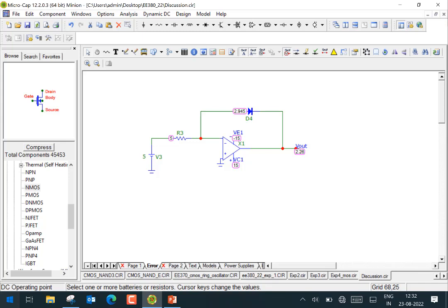No, power supply is also fine. You go and check. There is indeed plus 12. There is indeed minus 12. Power supply is also fine. So op-amp is fine. Power supplies are fine. Diode is connected in the right manner. We took out the diode and put a resistor there. If you put a resistor here, you would expect some kind of a negative voltage here, right? Still positive voltage. Still positive voltage, no virtual ground, right? So what could be going wrong?